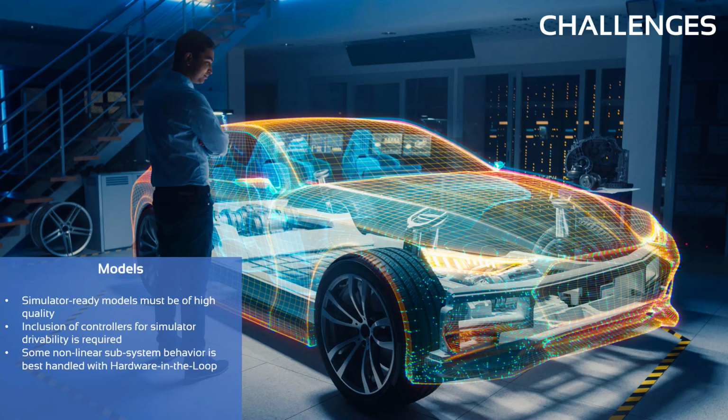It's common for models that are used for offline analysis to be brought into a simulator, and issues are identified that were missed or even intentionally overlooked in the offline environment. An example is vehicle dynamics models in Adams, or other multi-body dynamics tools, may be run offline without realistic traction control or ABS controllers included. Without those controllers, the real-time version of the models may be undrivable. Though higher fidelity models are needed and will take an investment, it's worth pointing out that this investment highlights the very aspects of the model that present themselves on the simulator that are critical and would present themselves in a prototype-based process as well.